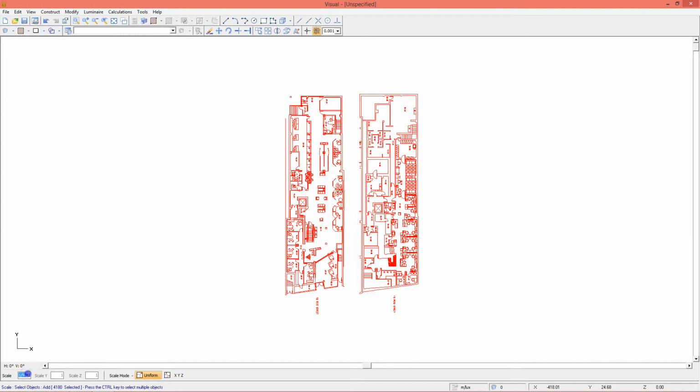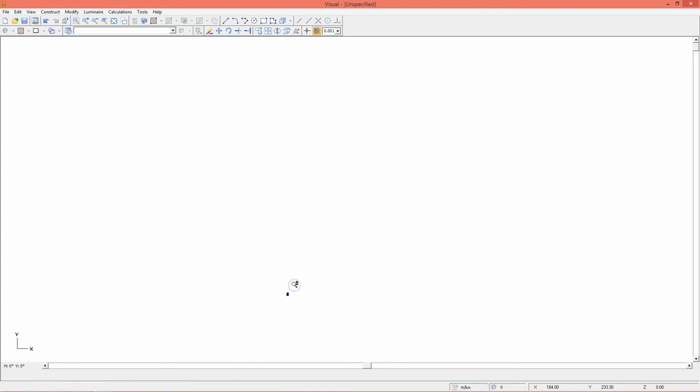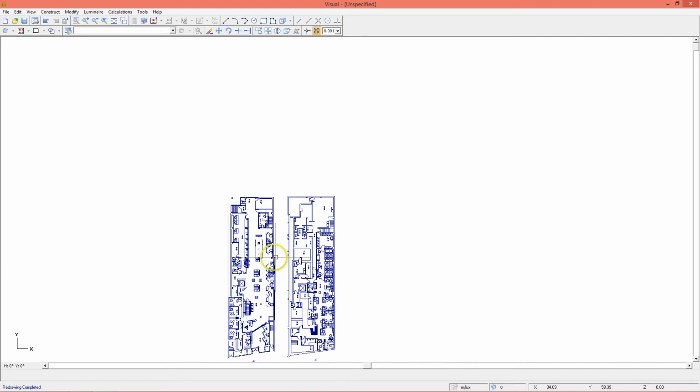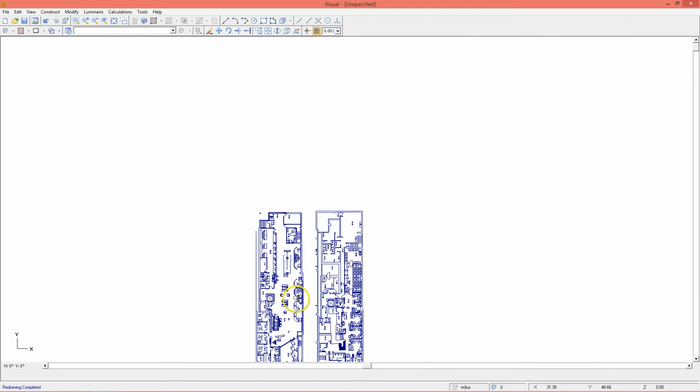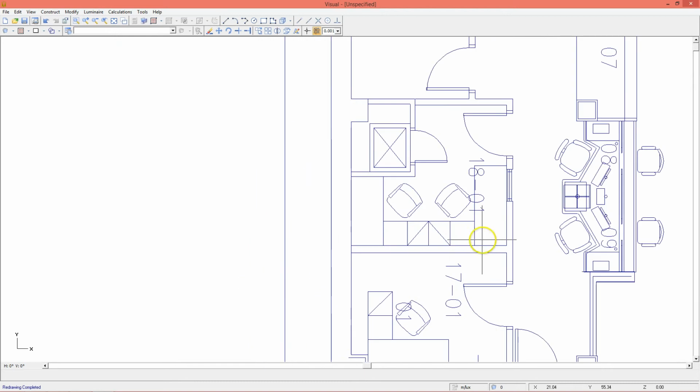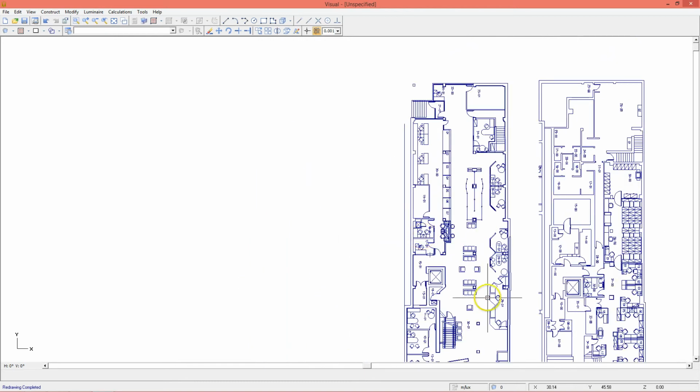Go back here. I start my base point, which will be at 0, so X, Y, and Z should all be at 0. Press enter, and there we go. Now when I bring in my light, it'll be to scale. Otherwise, before, the light would have been very tiny, because the light retains this meter measurement in the IES file.